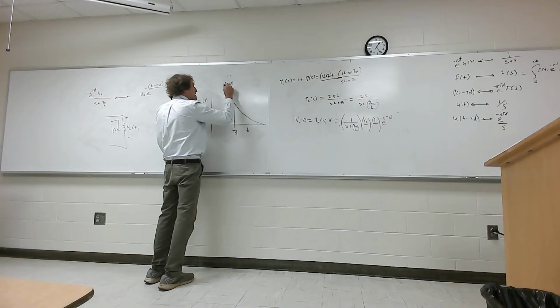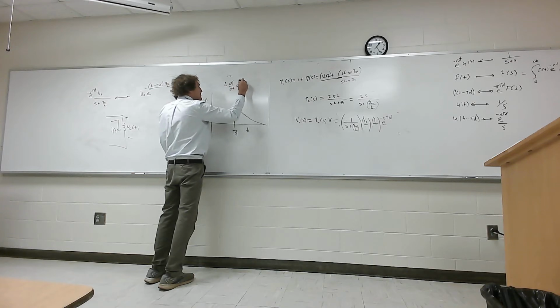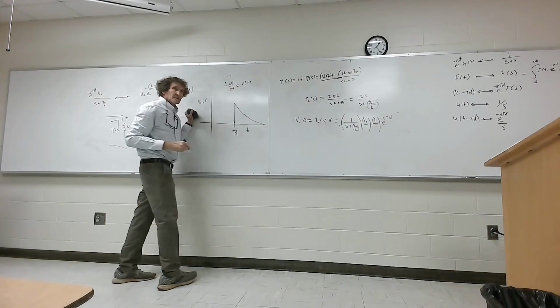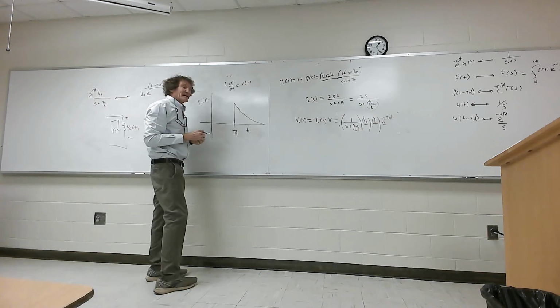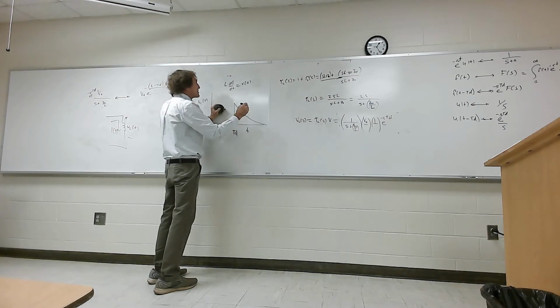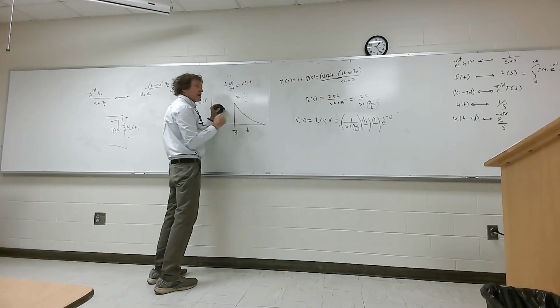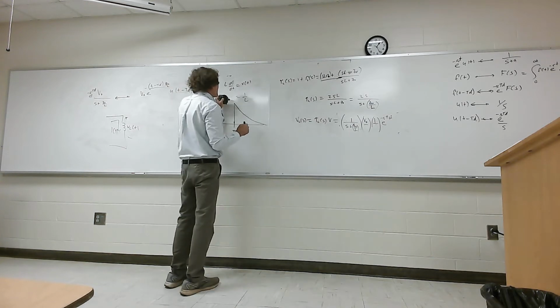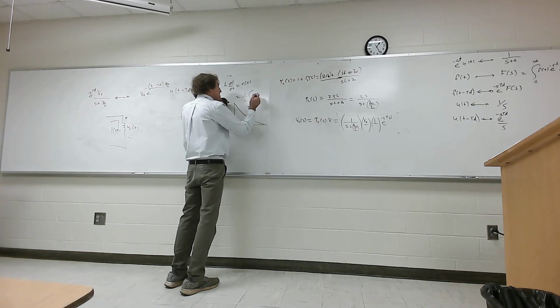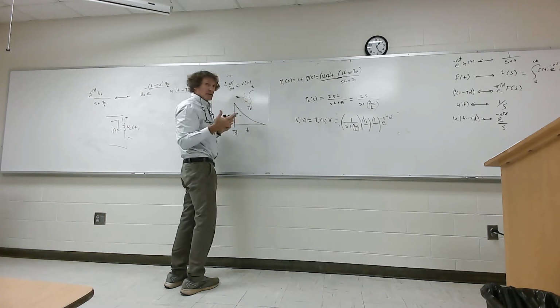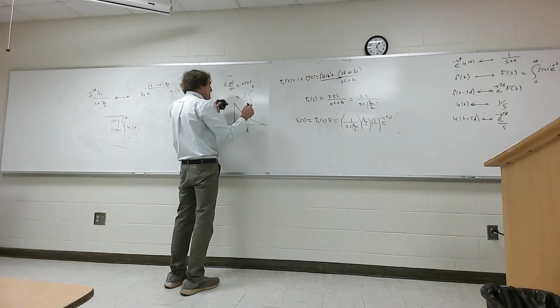L dI/dt is equal to V of T for an inductor, isn't it? Correct? Alright, so if I wanted I, what would I do? I would take 1 over L, then I take the integral from where the event started, TD, to when it ends, which is T. It would have to be for T greater than TD.